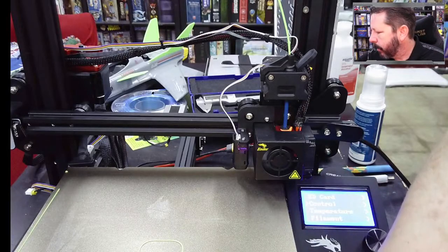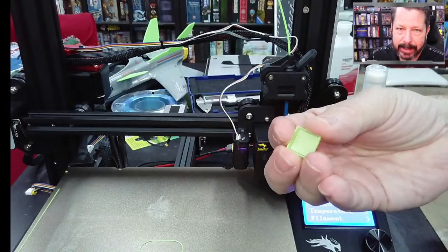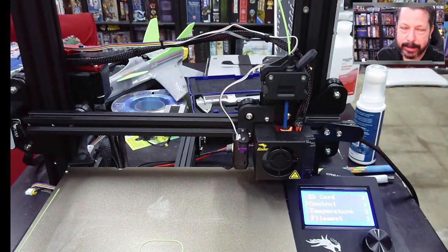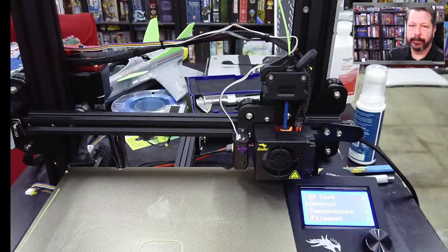And again, our little test, we kind of invalidated. For one, it's tiny, but we also sped it up to get it printing faster. So do it the right way. Check your flow rate and see what you're at. That'll get you your flow rate and your retraction dialed in pretty close. And those can be two of your calibration prints that you run.